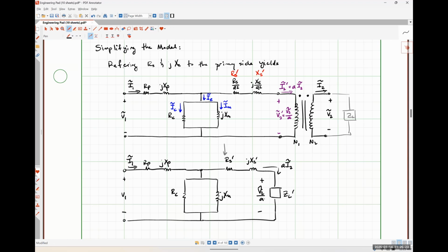If we just take into account the impedance transformations, the voltage transformations, and the current transformations when we're drawing our system, the information supplied by the transformer is completely redundant. Effectively, there's nothing connected to the secondary side anymore. So why does it even need to be there, is the argument that I'm making.